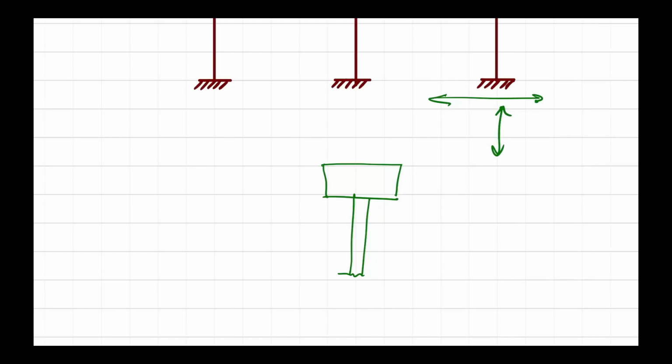Sometimes you design and you want the pile to be able to carry the moment. Sometimes you design the pile and the pile might not be cut below the ground. You might need the pile to just stick up above the ground. And the pile is not designed to carry that moment. So pre-stressing inside the pile is just for the transportation purpose and for the piling procedures.